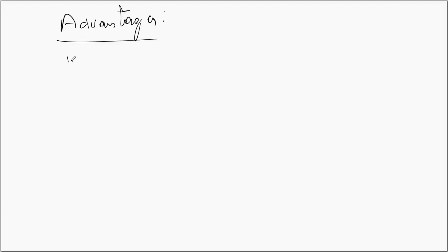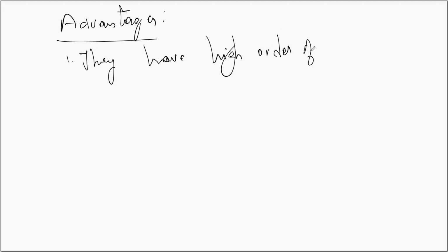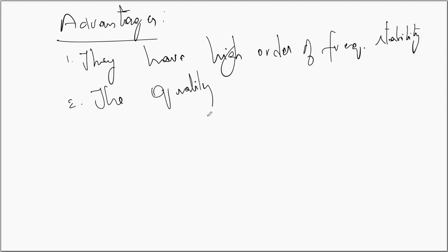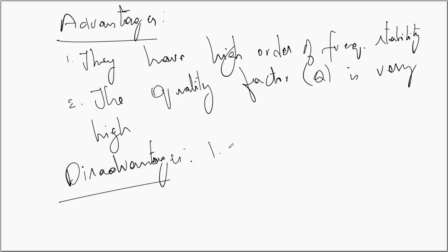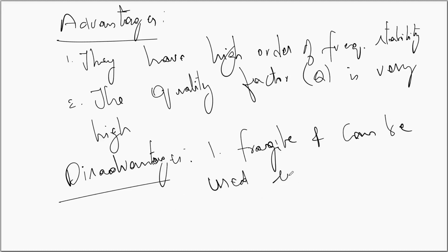The crystal oscillators have a high order of frequency stability. The quality factor of the crystal is very high. The disadvantages are, the first one, crystals are fragile and can be used only in low power circuits. Secondly, the frequency of oscillations cannot be changed appreciably.